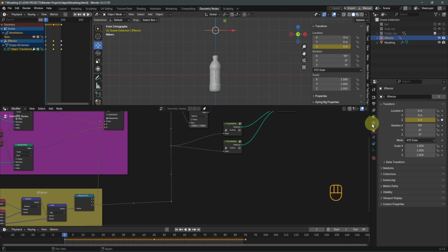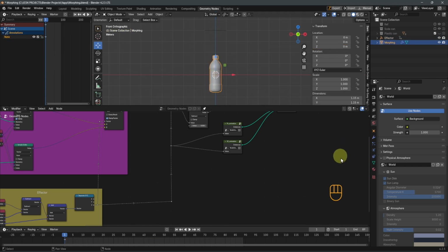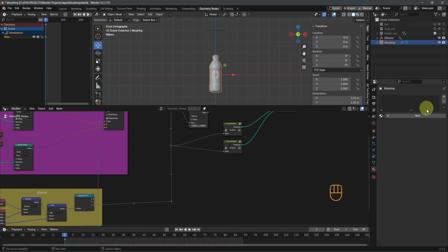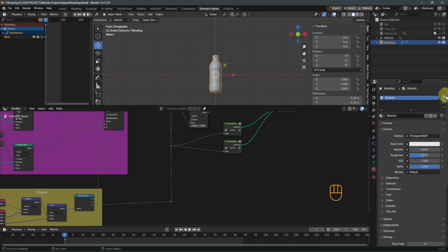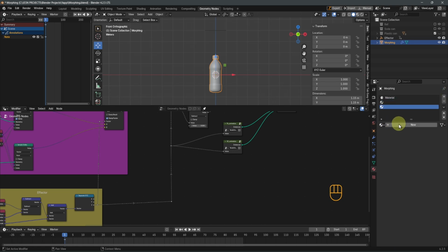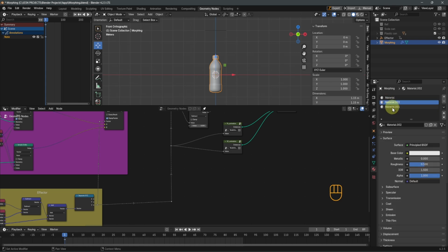So let's click and then come to the material menu, and then let's add in 3 materials, and then let's name it, let's see, let's name this one to be plastic can cover. Let's do MAT material underscore plastic can cover.